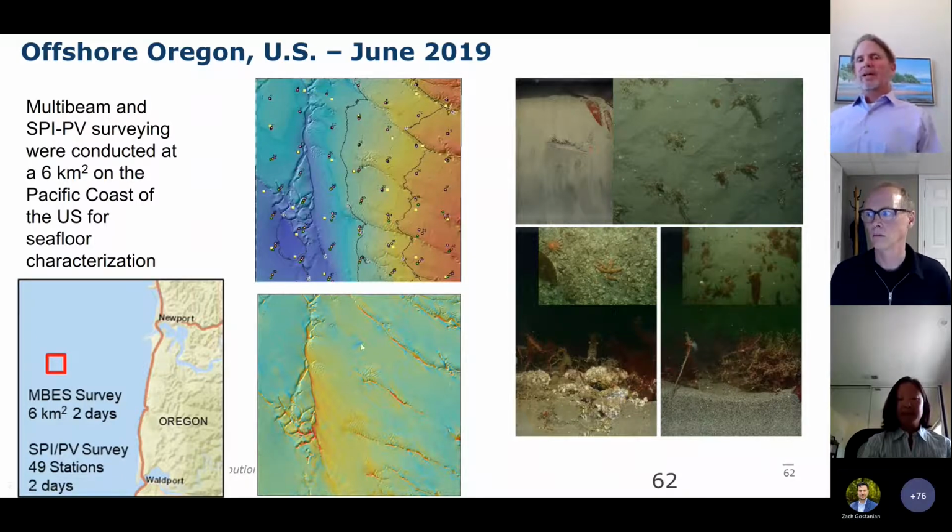The bluer areas are softer areas that are more absorbing of the sediment. Red areas are harder areas that reflect better. As you can imagine, sands and coarser sediment reflect better, where silts and things like that absorb the acoustic energy better. So here you can see the bright areas. Those are areas I showed as coarse sand earlier, and areas that absorb a little better.